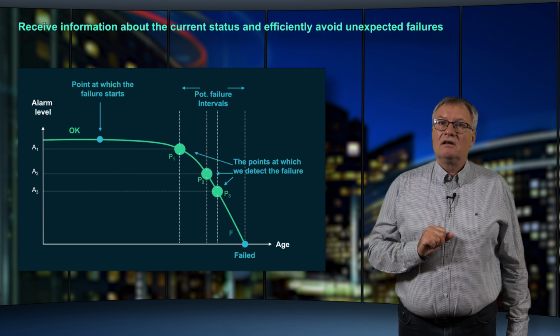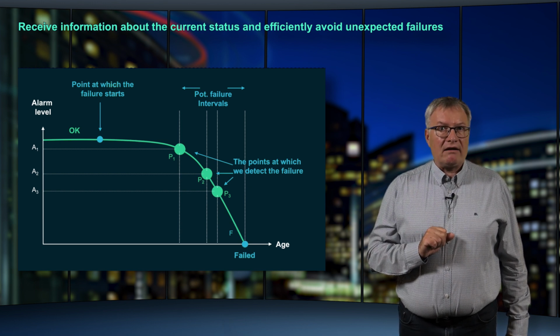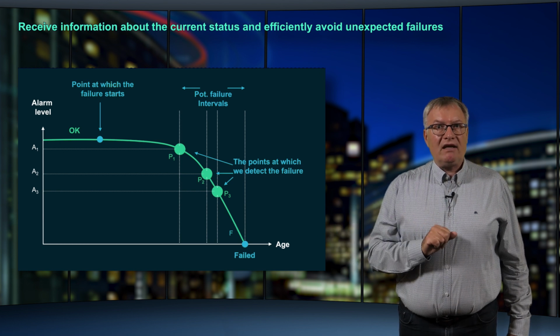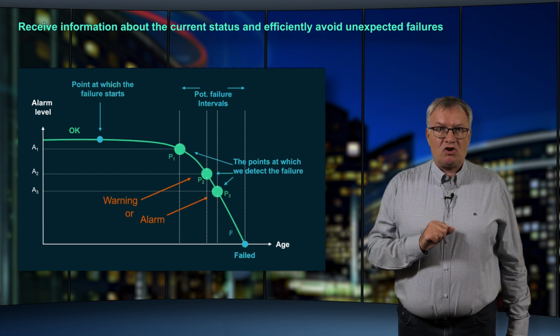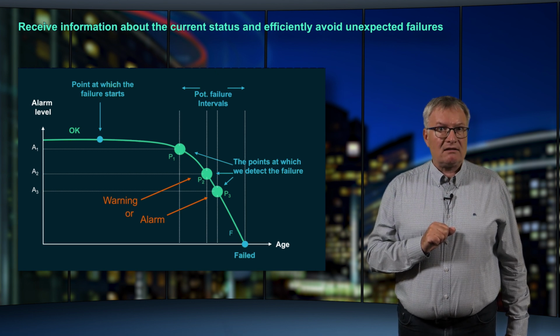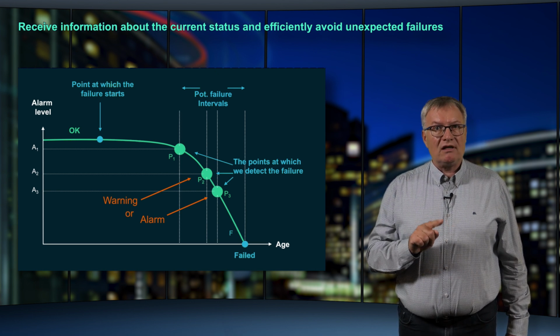These points represent potential errors that are recorded and reported due to integrated condition monitoring. The notification of a limit value exceedance can be done as a warning or alarm message. Maintenance measures can thus be planned before faults or downtimes occur.